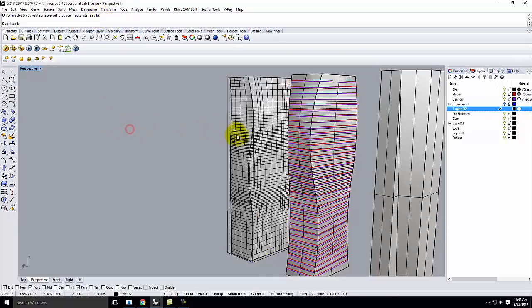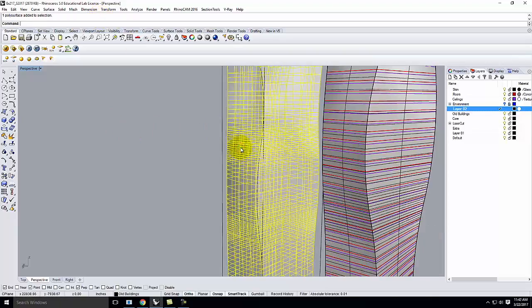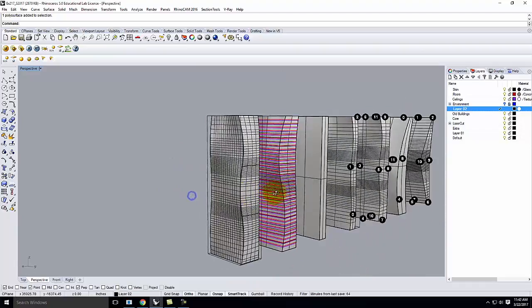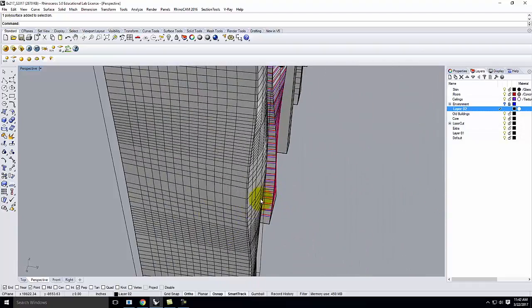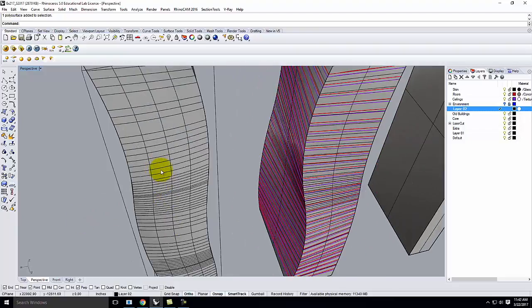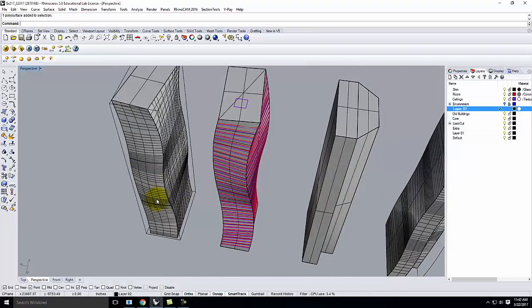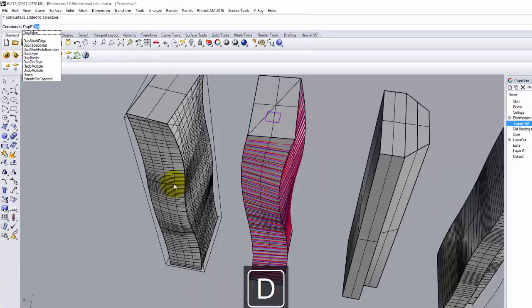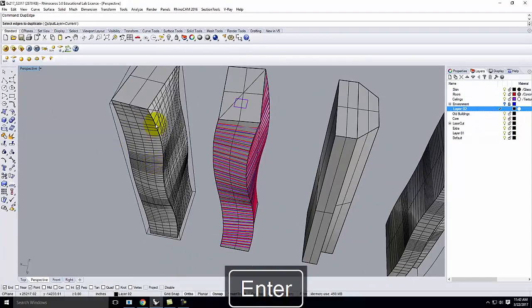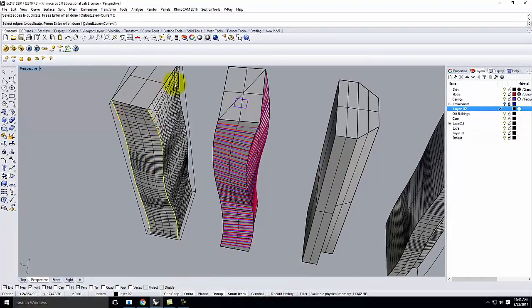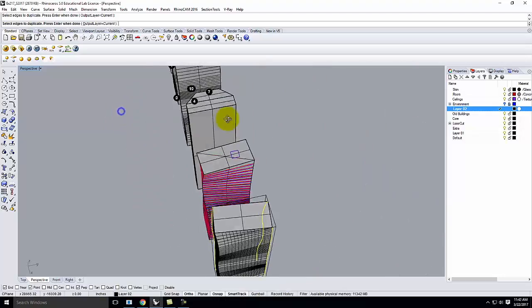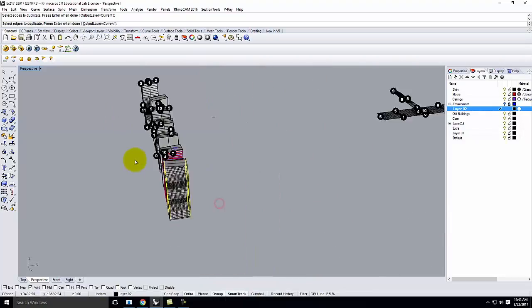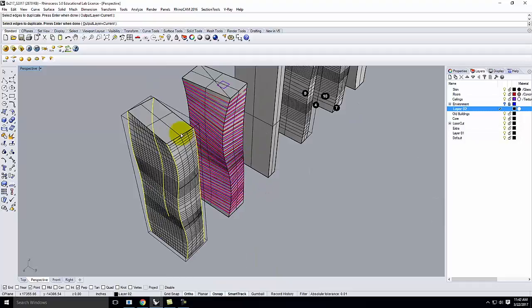So if your building happens to be like that, and it can be accidental, like in something like this, maybe I didn't mean to have that side pop out just a little bit, it just kind of happened when I did the cage edit. What that means is you have to go back in and recreate this particular piece. So what I would recommend is the dupe edge command, and create a duplicate of each of the 4 edges of your building. Or maybe you have multiple pieces and it would be more than that.